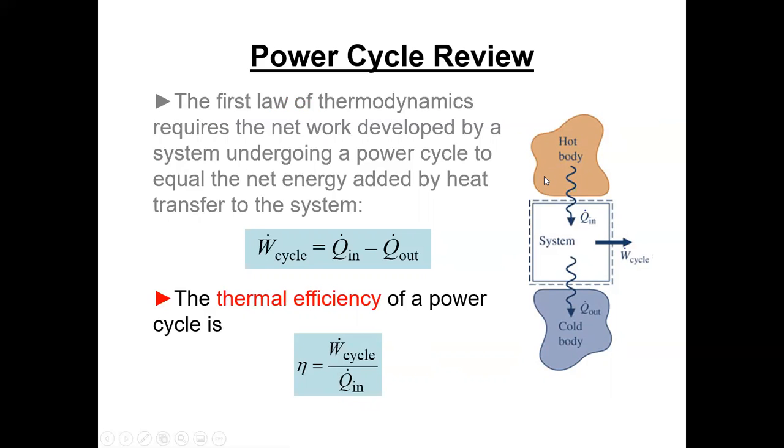But while it's interesting information, as you get to higher and higher temperatures, which are possible from the combustion side, you have all these materials, boiler tubes, steam pipes, turbines, and all this stuff, and there's some kind of practical limit on the materials that these things are made out of, and the longevity of the equipment, and how long it's going to be before you have to replace it. So in a lot of cases, the materials just don't support operating at higher temperature.